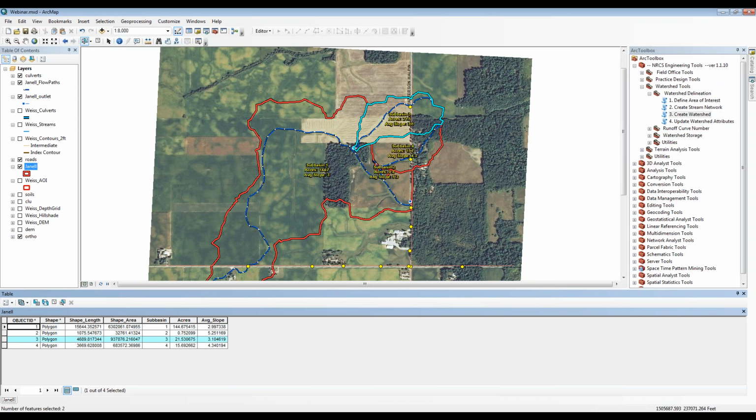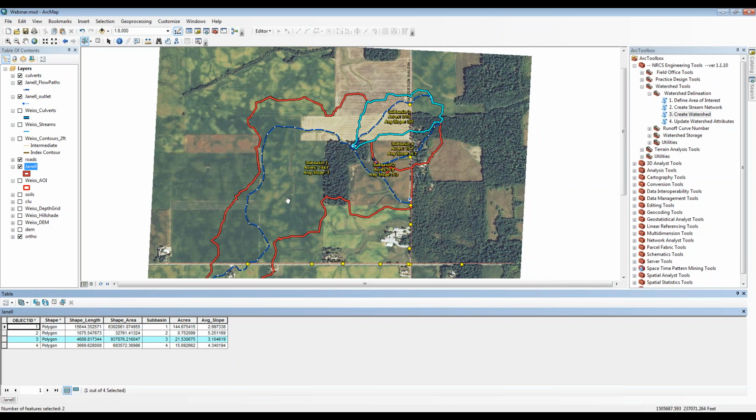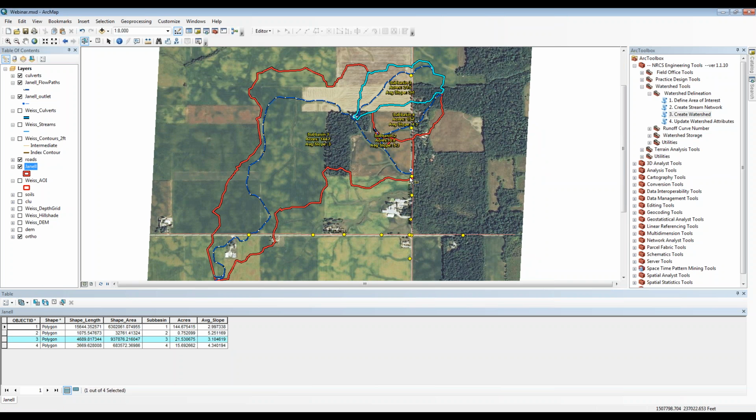Okay, so again, my suggestion, if you're going to do a design for like an outlet structure, pretend this is a creek and not a road, if you want to do some kind of drop box here or whatever, it would be good to have the overall watershed characteristics, and then for each lateral to have those sub-basin characteristics. Any questions on our basins to this point? If we want to pause, I'm pausing.